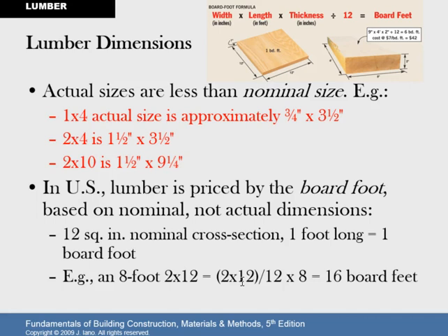All right, dimensions. Just important to know, when it comes to dimensional lumber, as we call it, there's a nominal size and an actual size. So a 2x4 before it's surfaced is actually 2x4, but after it's been surfaced, it comes out at 1.5 by 3.5. So 2x4 is the nominal size, 1.5 by 3.5 is the actual size. And all this pertains to all dimensional lumber.